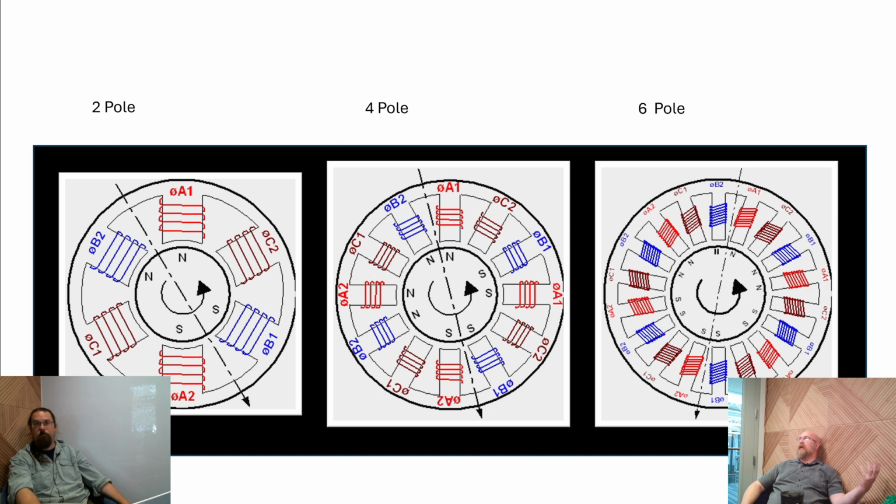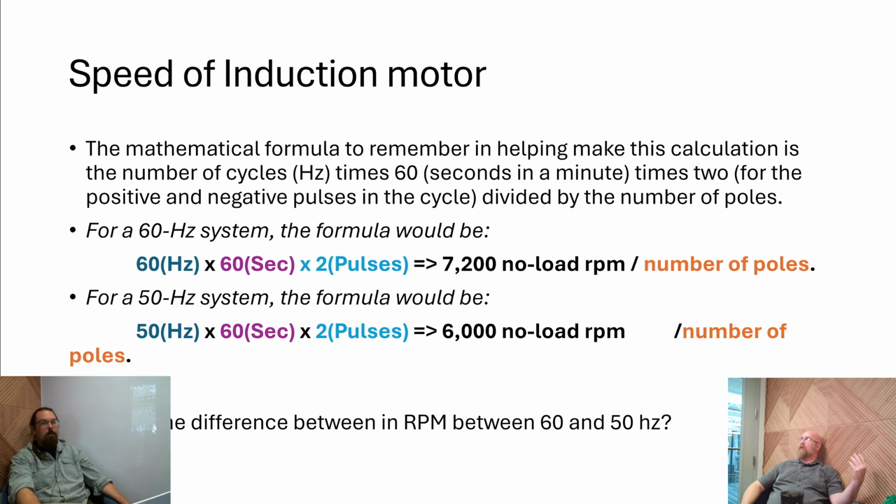Like, so you need to relate, oh, this is a 12 pole motor, and it's sounding like a 4 pole motor. That's not good. That means that something's like a bearing's going out.